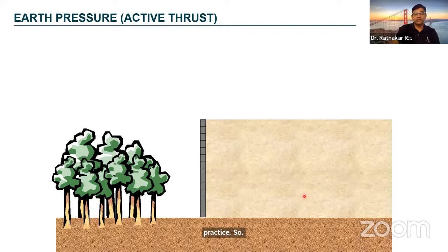Let's look at it. So you have a retaining wall, you have soil. For now, let us accept that when we have a wall holding a mass of soil, this soil produces a pressure against the wall, and in this case, it results only from the weight of the soil column. So we can say that the higher the wall, the bigger the earth pressure. It is very easy to understand that when we talk about vertical pressure.